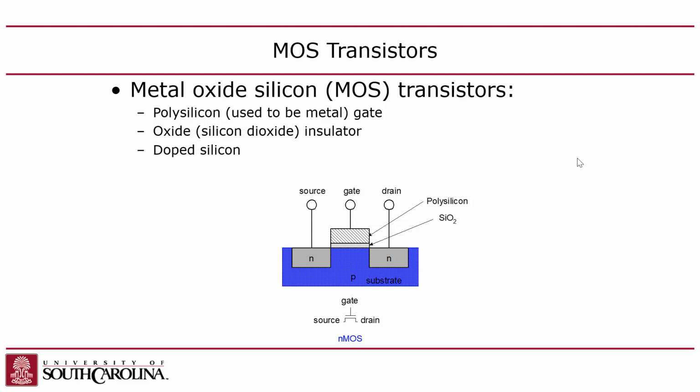So you don't have that happen, right? Now, that's still not without consequence. You may not be able to send current from the substrate to the diffusion area, but you still get a capacitor there, which has big implications, right? Remember capacitors: when you have two things next to each other where there's no direct connection between them, the dielectric is in the middle. So you do get a capacitor here, but they're not conducting, directly connected, right?